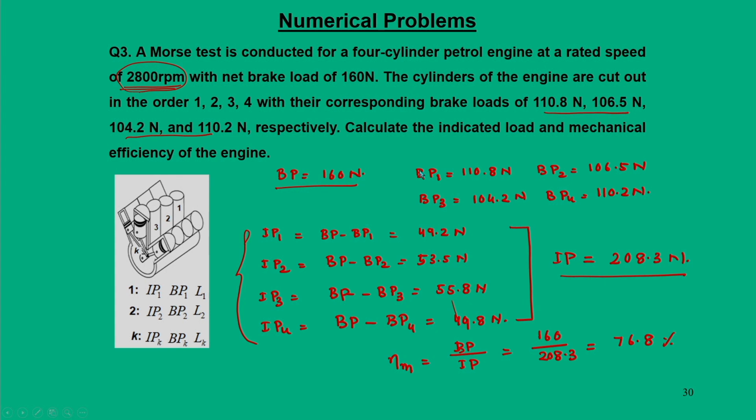In this way we can calculate the indicated load IP as 208.3 Newton, and the mechanical efficiency is 76.8%. So, with this I will conclude this lecture. Thank you for your attention.